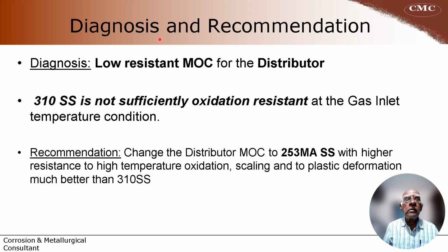And this is the diagnosis and recommendation. The primary diagnosis is a low resistance MOC for the distributor. You may recall the distributor is the plate formed with a series of holes inside. So 310SS is not sufficiently oxidation resistant at the gas inlet temperature at this operation.